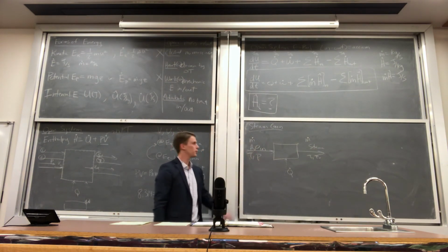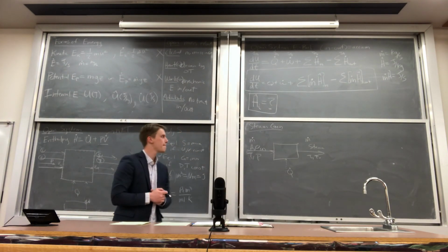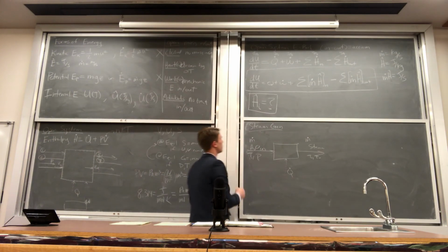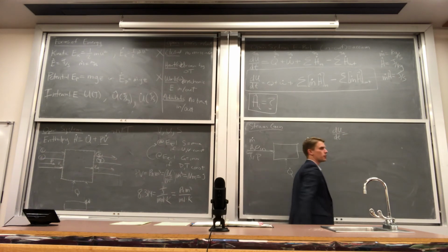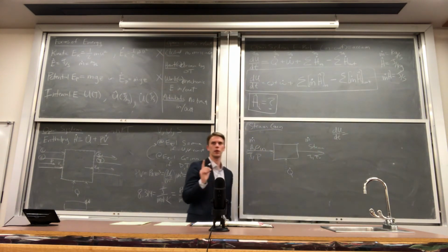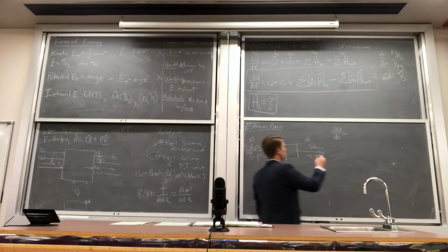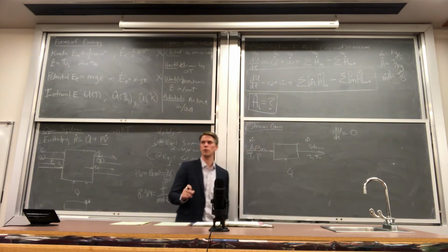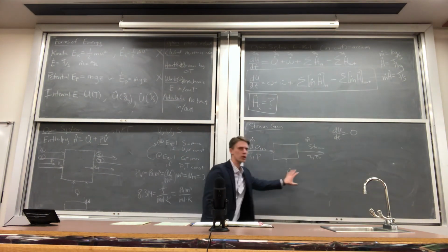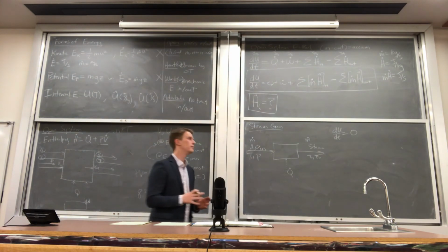Now, our material balance would tell us that in equals out, so that's taken care of. That's the trivial part. So let's simplify our open system energy balance. So let's start off. dU/dt. What is our first approximation that we always use for flowing systems? dU/dt is 0. Bingo. dU/dt is 0. This corresponds to a steady state process. There is no accumulation. So the energy balance works out perfectly so that no net energy goes into the system.